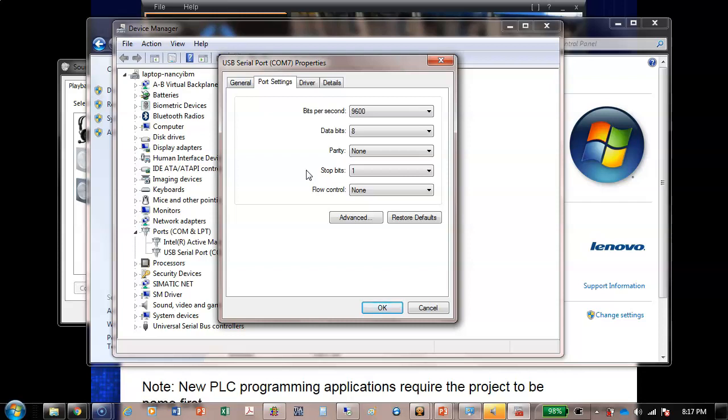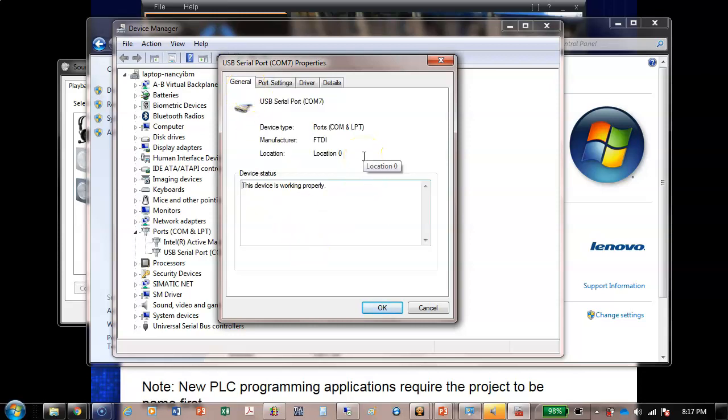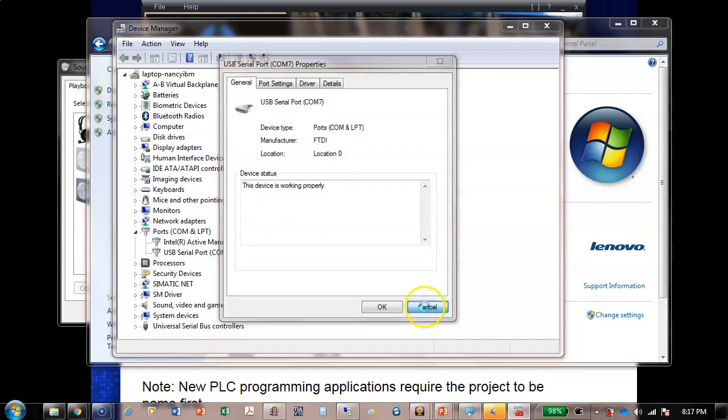So RS-232 or serial communication is pretty interesting. You won't have this in your list unless you have some type of dongle that uses this interface, and this one you actually have to install a driver for. So when you look at your Device Manager, odds are you won't have any COM ports. But I had to go here because my PLC was set to look at COM port 5, and what I found out was it was actually on port 7. As soon as I changed that, everything worked okay.